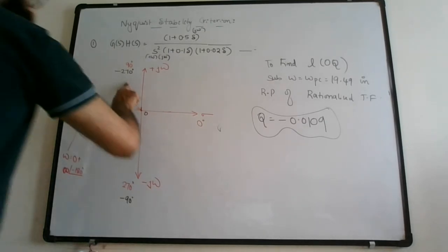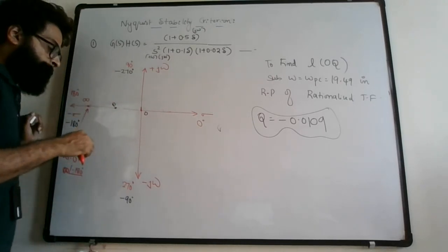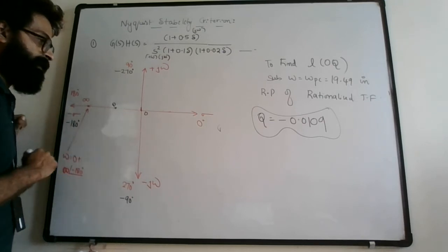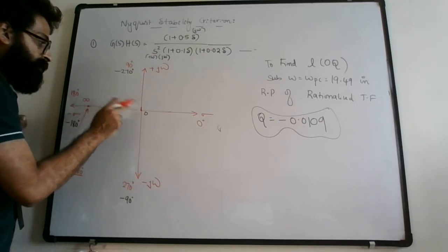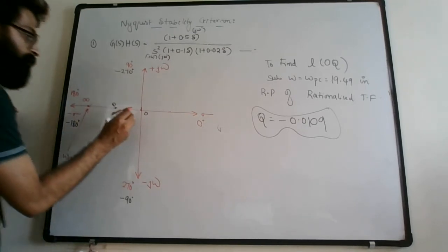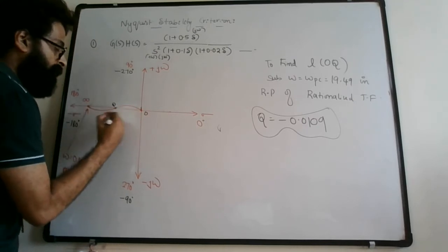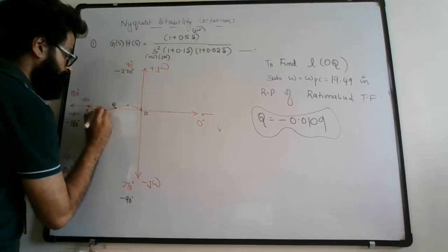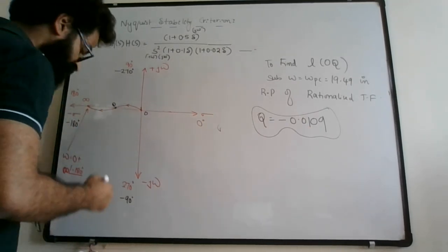So what you have to do is, in section 1, the magnitude was 0 at omega is equal to infinity, and magnitude was infinity when your frequency was set to 0, and the rotation is basically 90 degree clockwise, right? So 90 degree clockwise, so something of this kind you can draw. Clockwise is this sense. Fine, so that's your section 1.